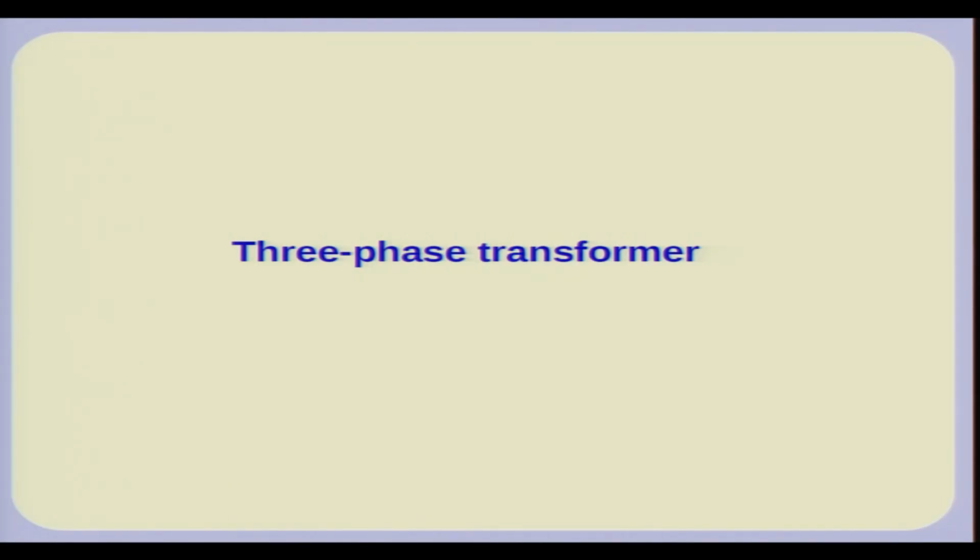So we will just have a look at what are the kind of connections you can have in a 3-phase transformer. Remember, you can have a bank of 3-phase transformers connected to each other, but remember that the return path can be common, the neutral path, you can have a star connection with a return path. The advantage is, of course, if you have a balanced system, the return currents through all 3 phases cancel out in case they are merged into one, because IA plus IB plus IC is equal to 0. Of course, it is not true always, but usually the neutral current can be smaller than the individual line currents, because they usually cancel out if the load is reasonably balanced.